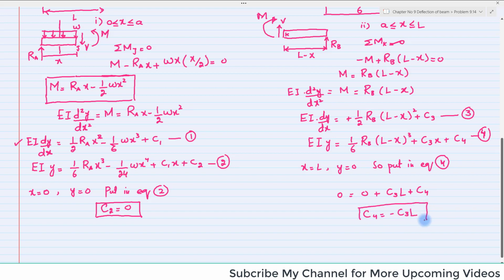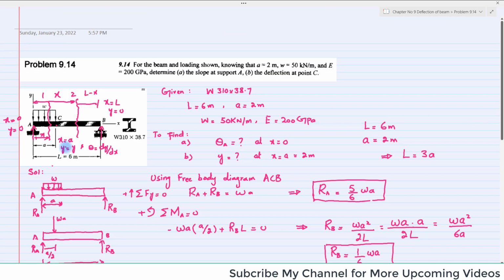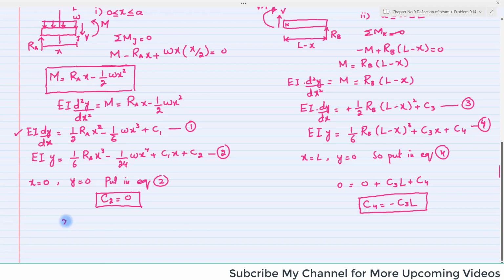But here again you can see you cannot find C3, C4, C1 as well. So what we will do is we will have a boundary condition. I will show you that at x is equal to a, we have y is equal to y and theta is equal to dy by dx. At x is equal to a, we have deflection is equal to y, and at x is equal to a, we have dy by dx is equal to slope.